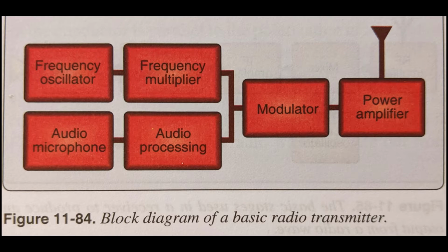Transmitters. A transmitter consists of a precise oscillating circuit, or an oscillator, that creates an AC wave frequency. This is combined with amplification circuits, or amplifiers. Other circuits are used in the transmitter to accept the input signal and process it for loading onto the carrier wave.